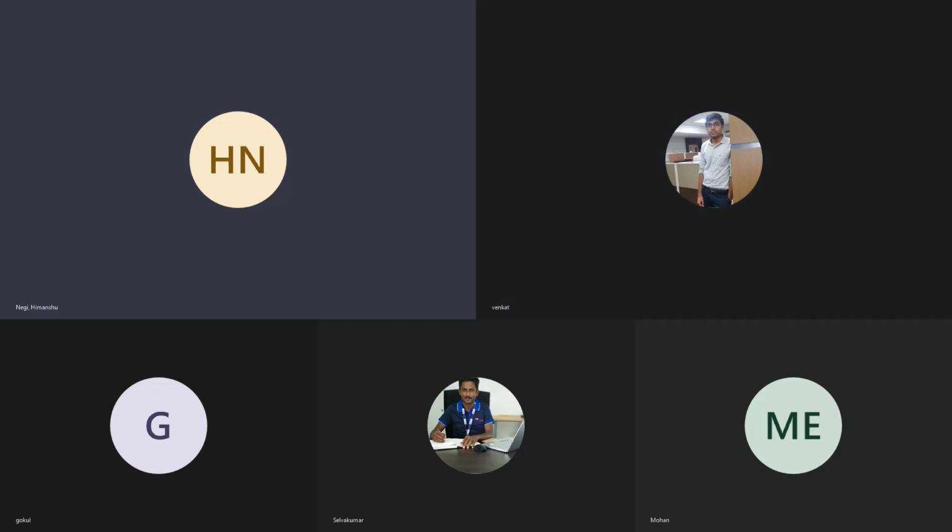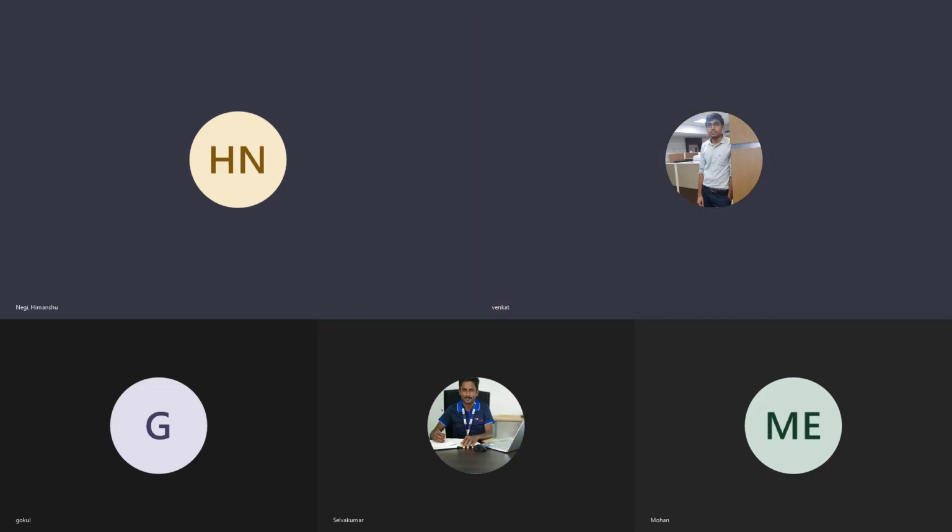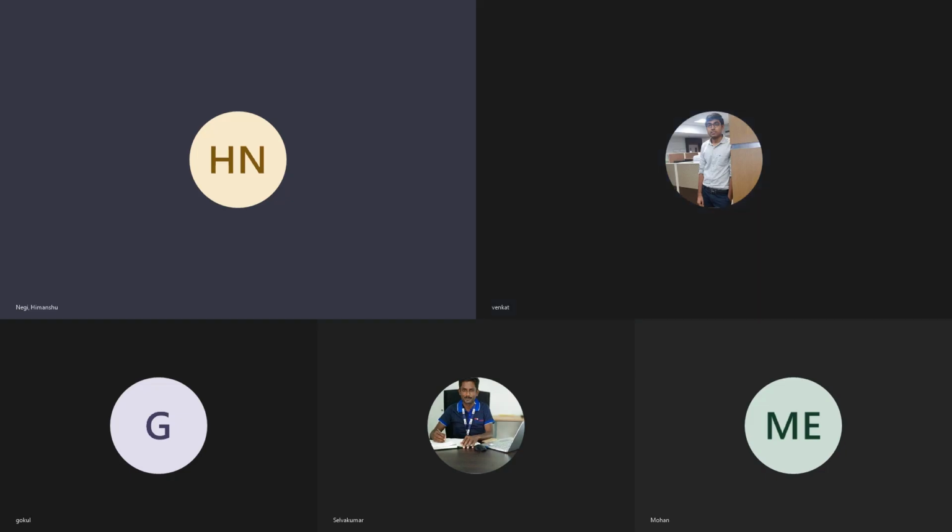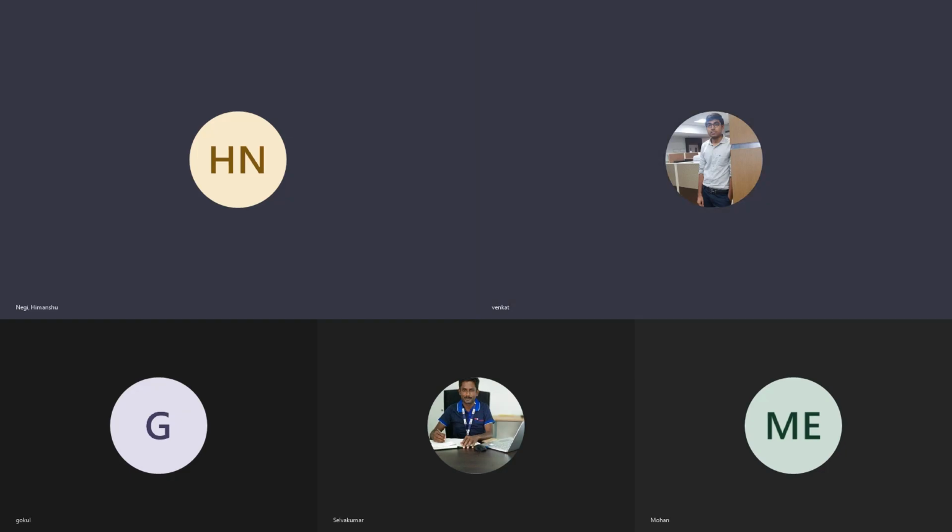They will give you the earthing specification, and they will tell you that the power frequency earth mat should be copper or steel, either way. And then the high frequency earth mat, they call it, should be below the power frequency earth mat, and this should be conductively connected to the normal power frequency earth mat every 3 meters or 1 meter or 2 meters.